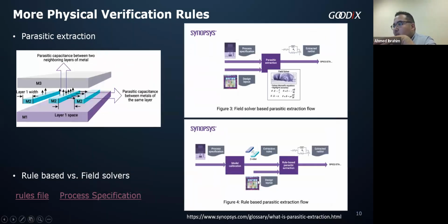So the tool takes the design and looks for some patterns and decides which R and C value will be suitable for that pattern or that geometry structure. And it produces the final extracted netlist based on that. Of course, this approach is not accurate, but it is efficient in case of digital flows, low frequency, and indeed can extract a complete chip at once.